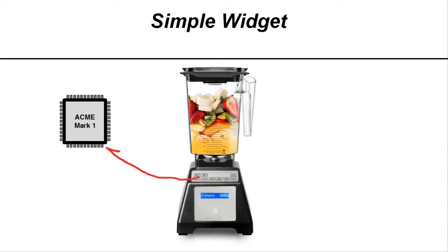So the buttons, that would be just digital inputs. I'll just say digital DI. Now then, it also has to control the screen. This may be a serial port, so we'll say UART. Now, if you don't know what UART means, the great part about Google is you can just search for it. It's a serial port. We use that for the microcontroller.